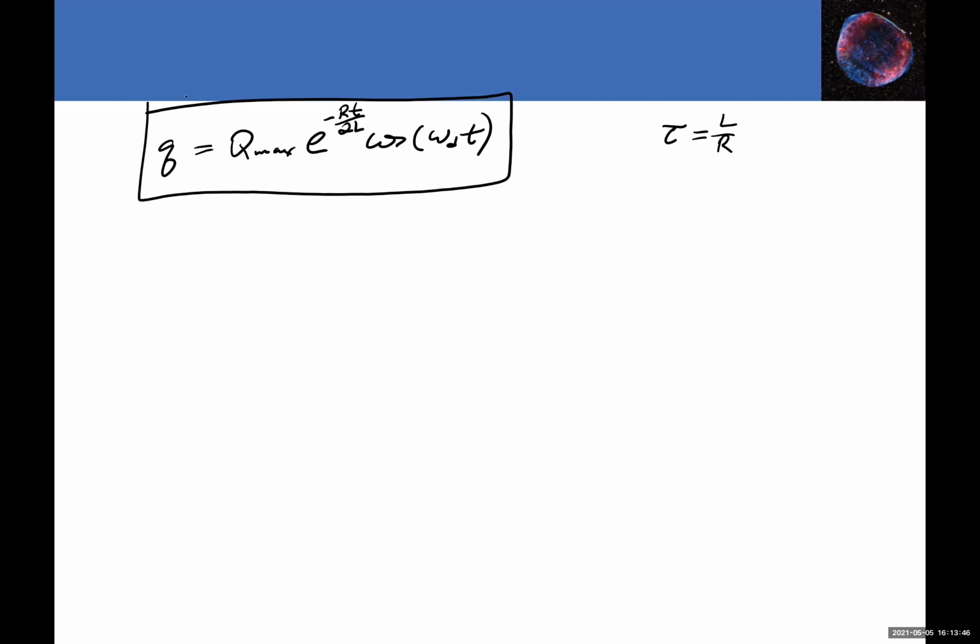Now, omega D is equal to, since this is not the same angular frequency that we had for the LC circuit, because now there is a dissipative component, the square root of 1 over LC, minus R over 2L squared. And this is all inside the square root. That means what we get here is the equation for the RLC circuit.